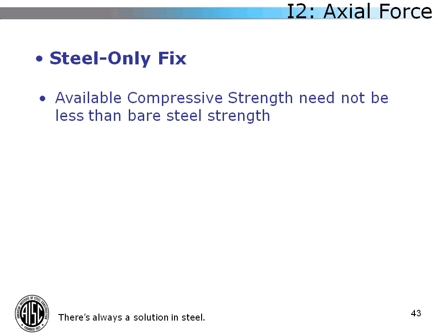The reason that this happens is due to the difference in resistance factors between non-composite and composite design. For non-composite columns, you're using a phi factor of 0.7 or 0.9. For composite design, you're using a phi factor of 0.75. So when you have a thick-walled member that is dominated by the steel strength, the addition of that little bit of concrete was not enough to overcome the difference in the two phi factors. So that was fixed in 2010. A sentence was added that just says the strength need not be less than that of the non-composite member. This is also addressed within the 14th edition steel manual, where all the tables for filled members in compression have a line within them that delineates the difference between the non-composite member strength controlling and the composite strength controlling.